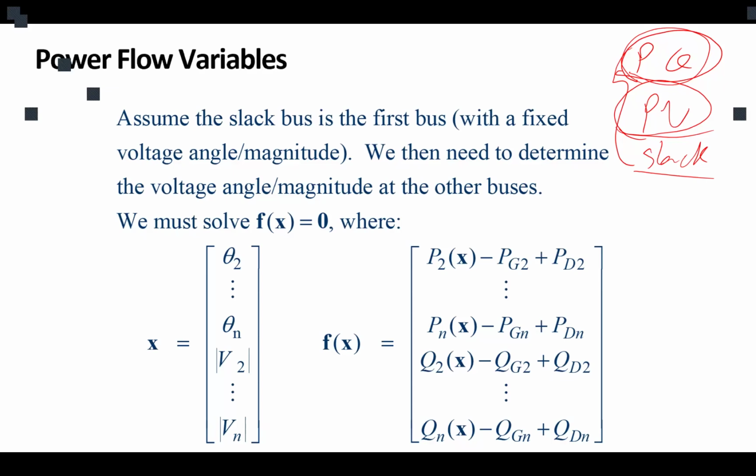But it wasn't asking me that, because I already chose P. What I'm saying is, it was asking what the per unit voltage was, I think in the load block, not on the bus. Okay, in the load block, you put the load as 0.9 per unit. That's the situation of your system. Your slack bus is always 1, but the rest you decide, or the grid decides.